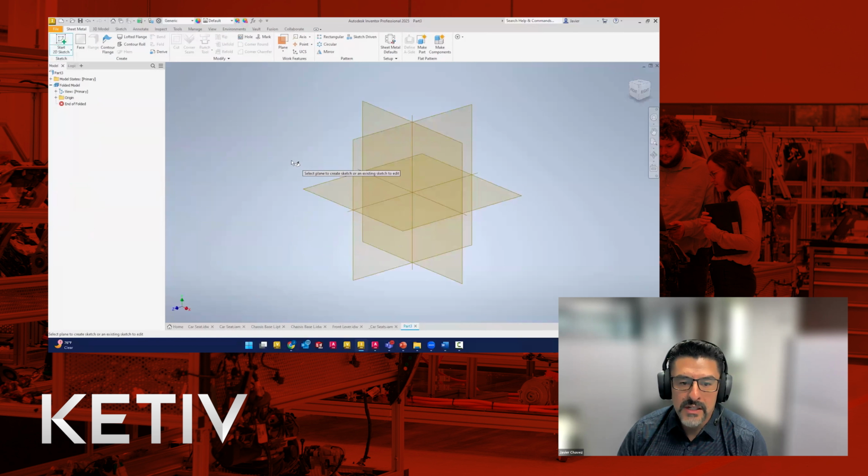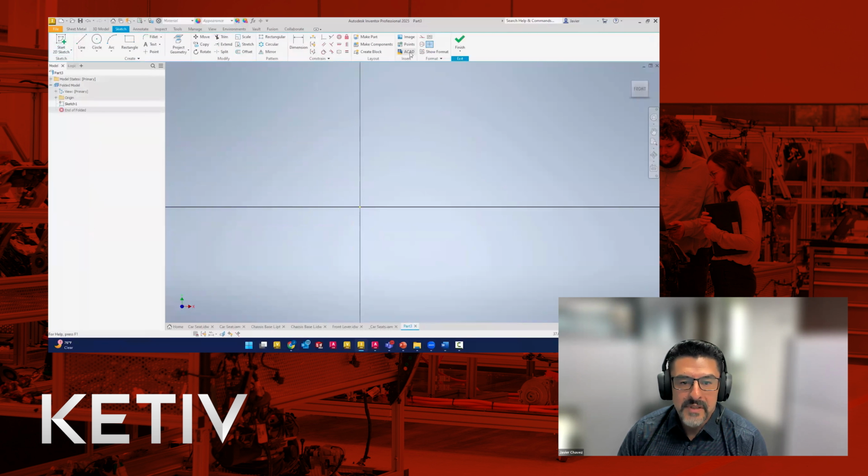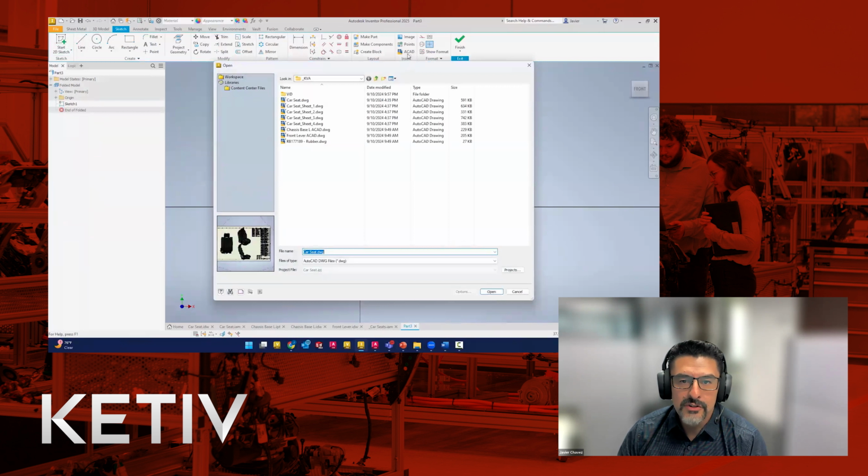And we're going to start with a brand new sketch, just like we normally do. Maybe your standards say the front face is always on this front XY plane. So we'll still do the same thing you normally do with 3D modeling, assuming you've gone through some basic training. And there's tools that we can leverage here, an import tool specifically to bring in AutoCAD data.